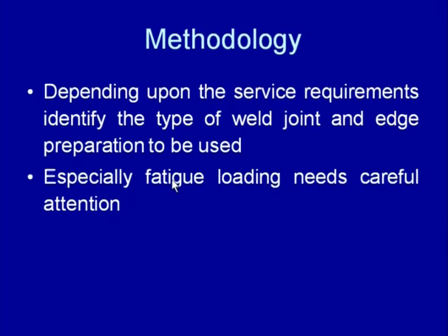Similarly, the edge preparation is done in such a way that full penetration can be achieved for a given plate thickness. The edge preparation must be done in such a way that it develops minimum residual stresses, requires minimum weld metal, and at the same time full penetration is achieved effectively for developing a full penetration weld joint. So, especially under fatigue loading conditions, these aspects require full and proper consideration, especially as far as the selection of the type of weld joint and the edge preparation is concerned.